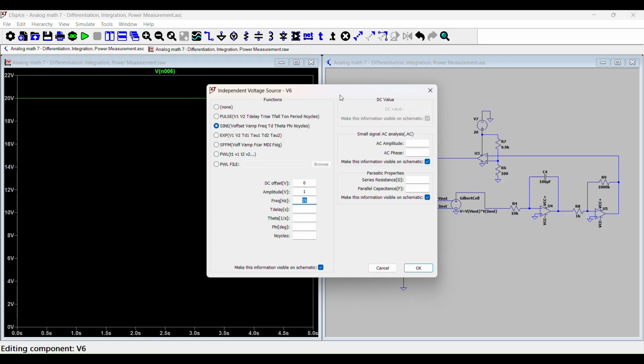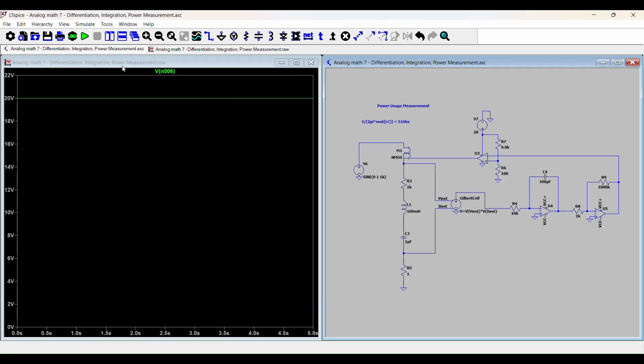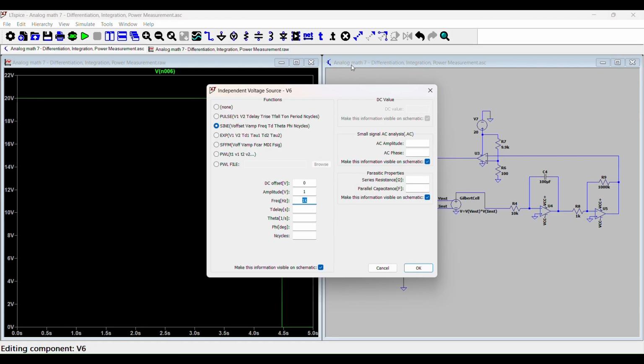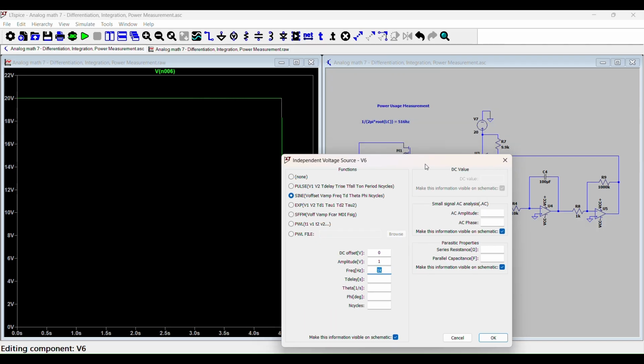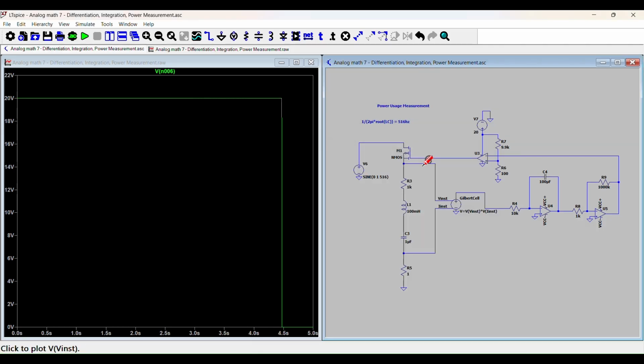And then if we look at 1K, let's run that. There you go. So it hits the threshold and we turn off the circuit. It hits the threshold at 4.47 seconds. So what if we put in the resonance? Theoretically, this should shut off faster than 4.47. So if we put that in and run, there you go. So it is faster. It's a little bit faster. It's 4.3 instead of 4.47.